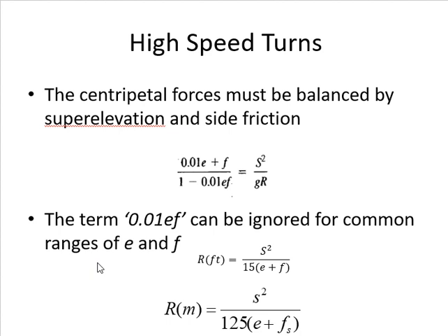Again, what's the reason here? To give us extra force to push the vehicles towards the curve. So it's always towards the curve. If I'm turning on the right hand side, then the superelevation will be towards the right hand side. So the vehicle has extra support in turning. Superelevation is providing us the positive push that we need.